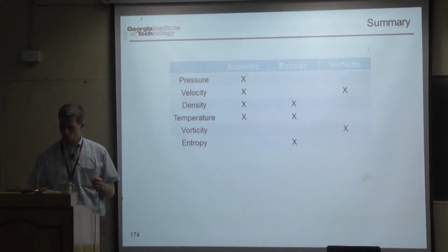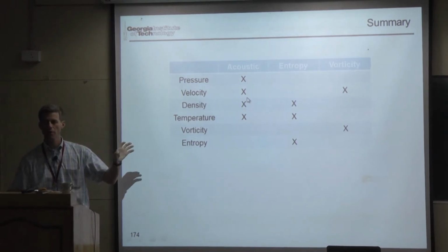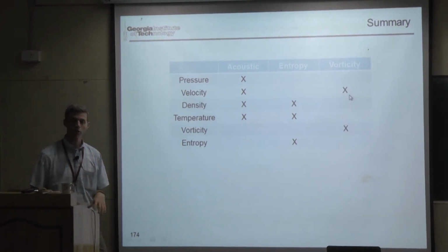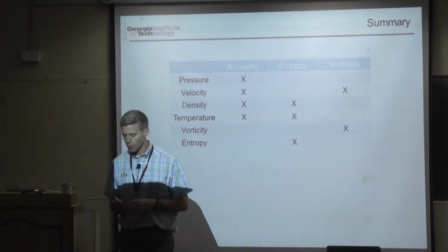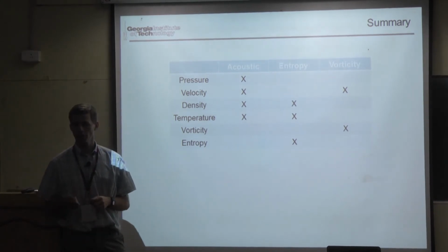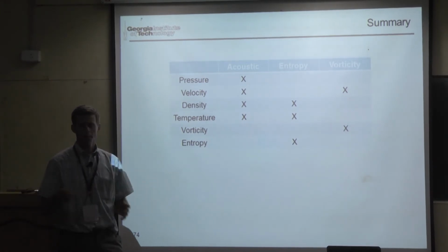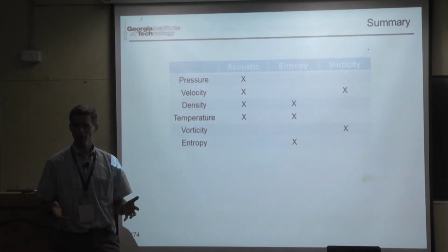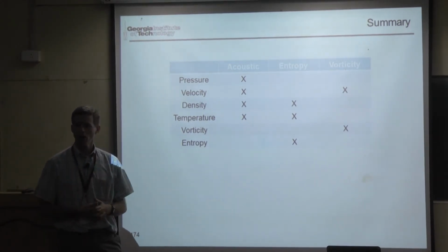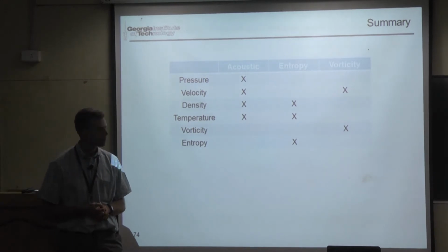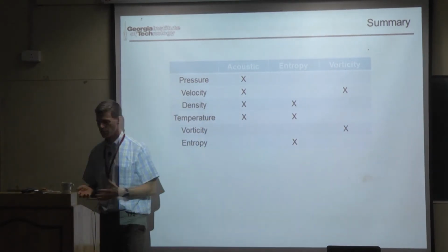All right, so that's one piece of the velocity field, which only cares about what's the sound speed field, what are the boundary conditions. The other piece of the velocity field is the vortical disturbance field, and this is profoundly sensitive to the details of the velocity field. And that is because how do vortical disturbances move? They're moved by the velocity. If you got 10 different mean velocity fields, you could have 10 completely different patterns of vortex convection. And so, two completely different sensitivities to the details of your flow field.